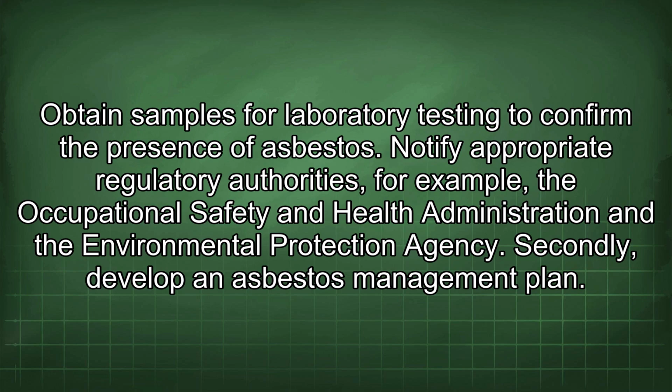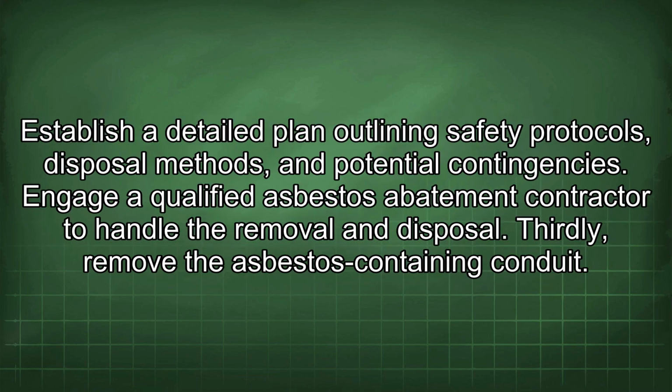Secondly, develop an asbestos management plan. Establish a detailed plan outlining safety protocols, disposal methods, and potential contingencies. Engage a qualified asbestos abatement contractor to handle the removal and disposal.